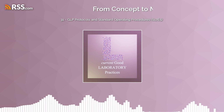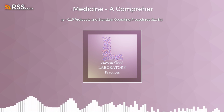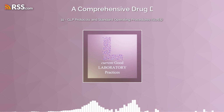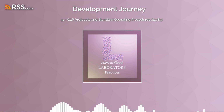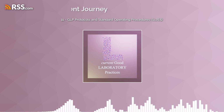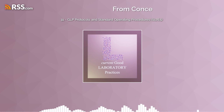And on top of making sure the equipment is qualified, there's also calibration. How does that fit in with everything else? Good point. Calibration is about making sure that the equipment is giving you accurate and precise measurements. You see, regulations require all equipment to be calibrated before it's ever used, and then at regular intervals after that.